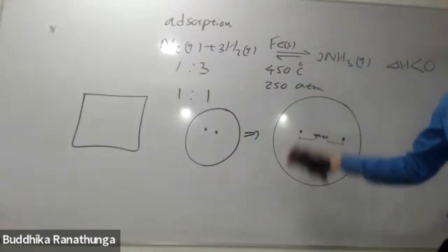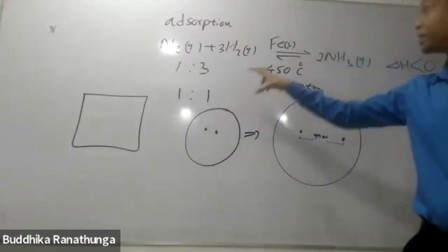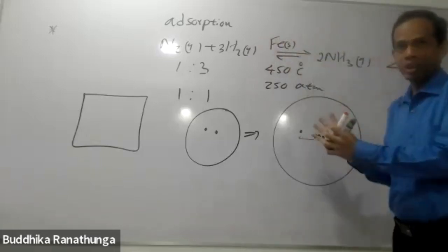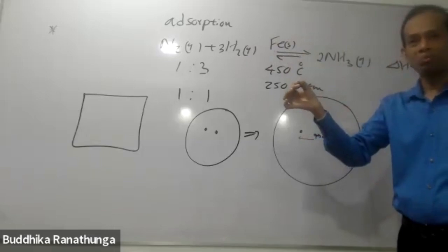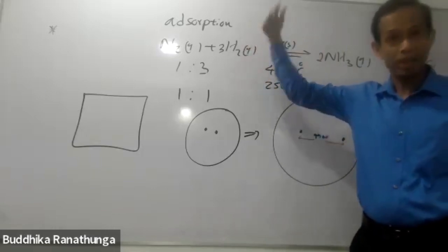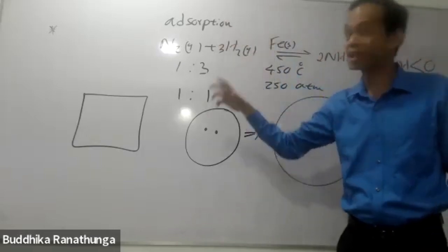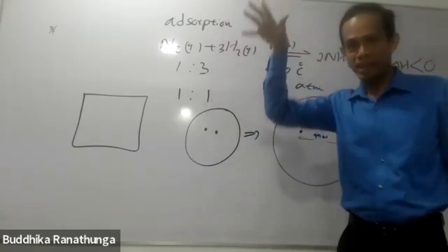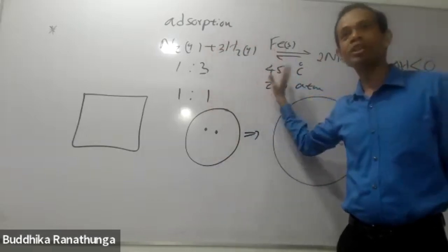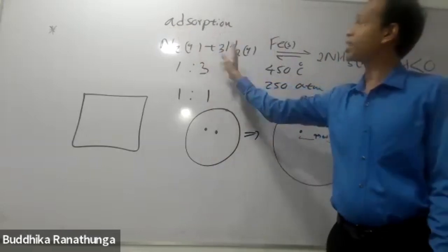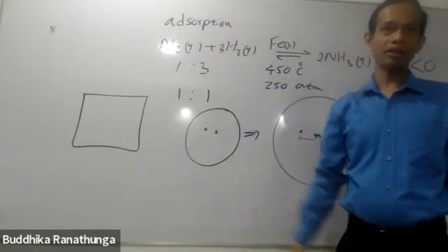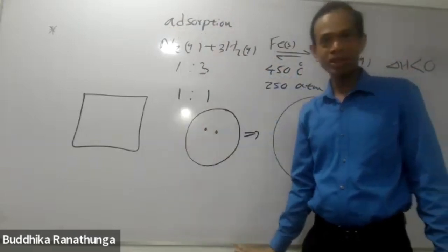Okay, right. Then anyway, this gas mixture is highly compressed, right? So you allow a certain amount of pressure to drop, and at the same time the temperature drops, then you get only ammonia liquefied. So nitrogen and hydrogen remain in the gaseous phase, so they can easily be separated, and this can be reused in the industry, right? Okay, is that clear?